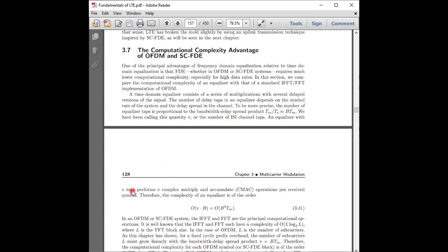And the filtering is a MAC operation, right? Filtering, summation of x of k h of n minus k, is a MAC operation, multiply, accumulate, and we know how complex they are, whereas OFDM is an FFT IFFT operation. Remember, we had this problem of circular convolution property. The circular convolution property is supposed to